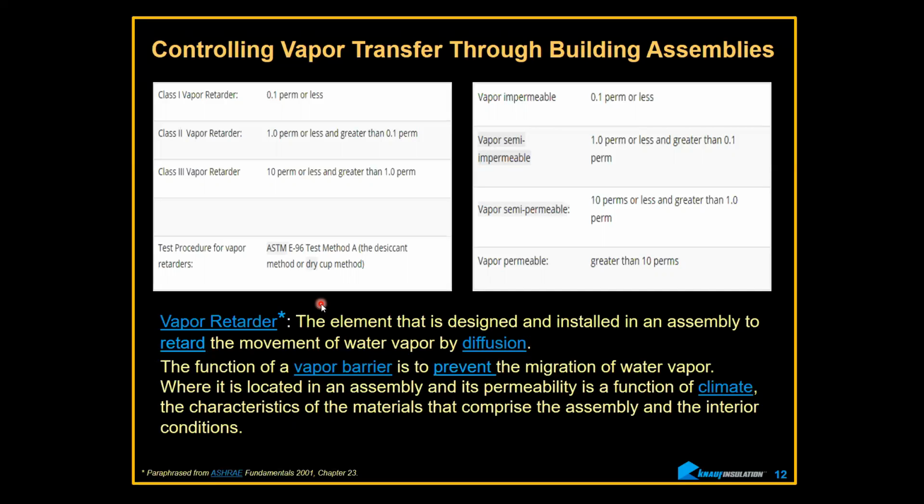And yes, they don't let any water out, but they don't let any more in. And then the next step is as it dries, these pores open up and the water gets transported out, back out. And that's what we're looking for. So it's actually a variable vapor retarder, kind of like all these new smart vapor retarders, smart air barriers. So they slow down and control. It's a valve or a throttle.